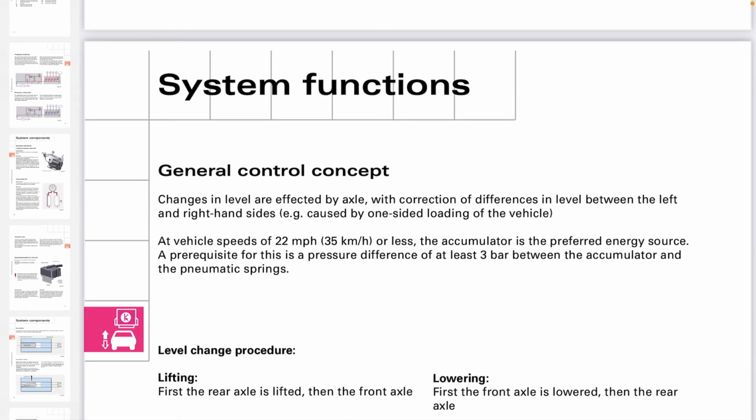But me personally, I leave the knob, the MMI, on comfort mode in order to minimize the system interference on everything, because on automatic, if for some reason I go up more than 120 kilometers an hour for more than 30 seconds, the system will lower the car, and then when I stop the system will raise the car,